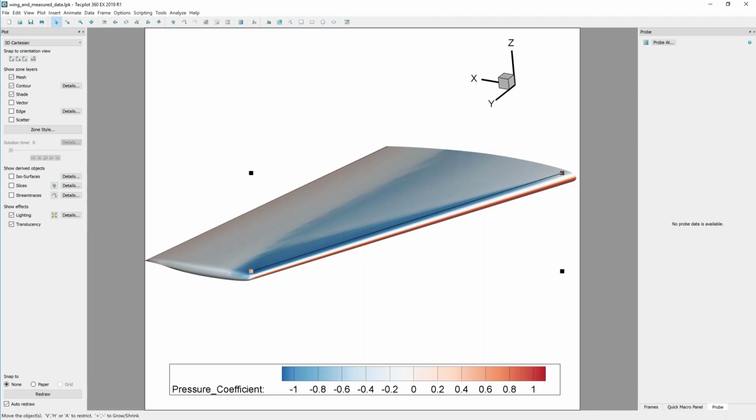And when I select that, I can right click and say extract points. This gives me the option of how many points along this line I want to extract. I can extract an even number of points spaced evenly along that line, say 200, or I can extract the points that define the geometry. I defined this only by two points, the start and the end. So if I want any of the data in the middle, I'm going to select regular points along that geometry. And I'll hit extract. The extraction is now complete.